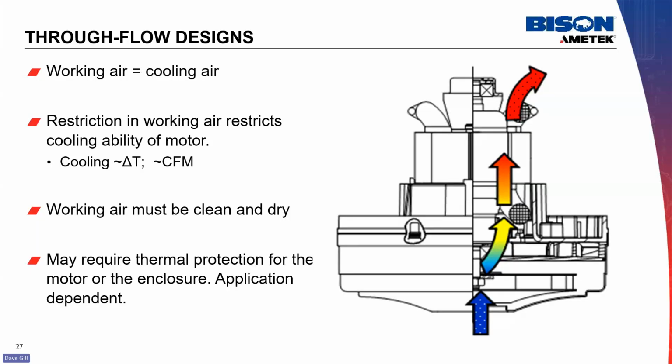Luckily, this is partially offset by the high airflow or CFM typically seen in working air. The problem comes when the working air is restricted either by design or by a change in the operating conditions, like filters clogging up and reducing that cooling flow. Many applications and regulatory agencies require through-flow motors to have some sort of thermal protection on board to protect the appliance and/or the motor by tripping when overheated.